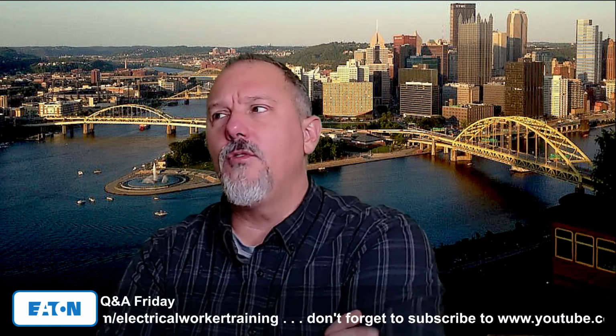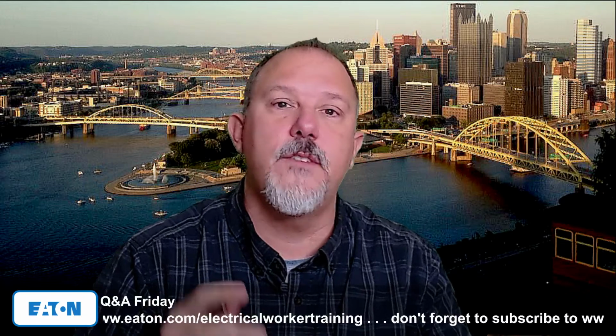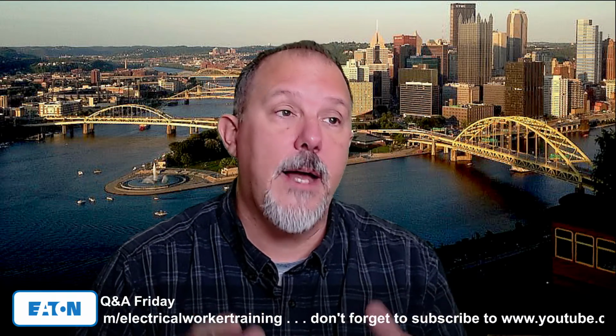So think about what we typically will do. We do test it inside of an enclosure. We test breakers in free air, but we also test them in an enclosure. For example, 80% versus 100% rated circuit breakers. In a 100% rated circuit breaker, I'll not only tell you the size of the enclosure that you need, but I'll also tell you the copper that you need, copper bus, and maybe a high density copper bus at that.